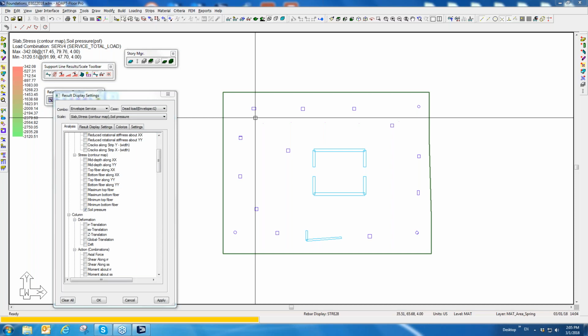Typically, the punching of a pile cap is made on the basis of you're checking punching for the reaction, not necessarily the support. So in that case, I would say it's critical for you to check that, but it would not be checked in ADAPT if you don't model the physical columns below the pile.